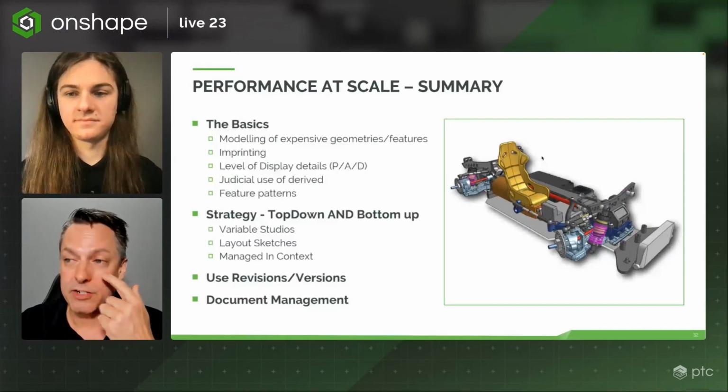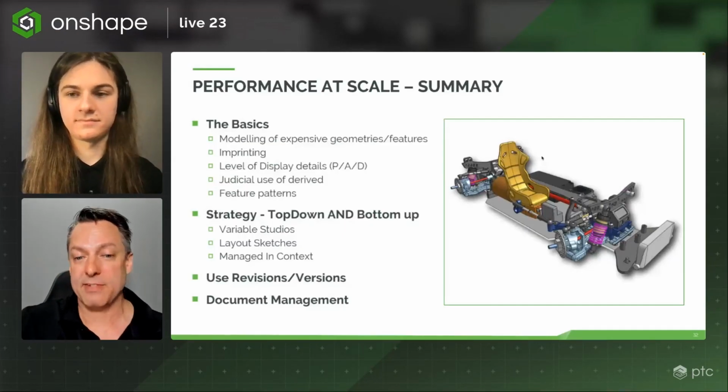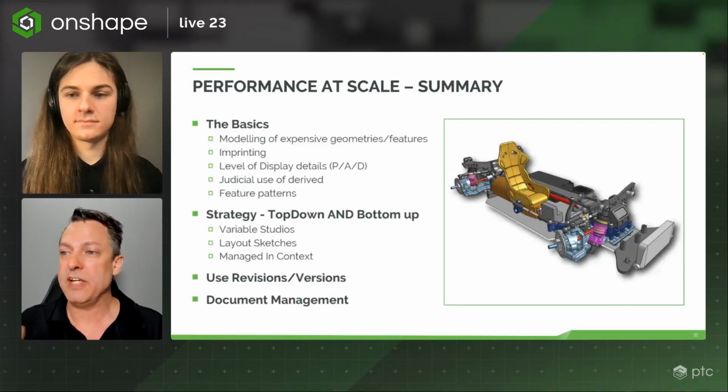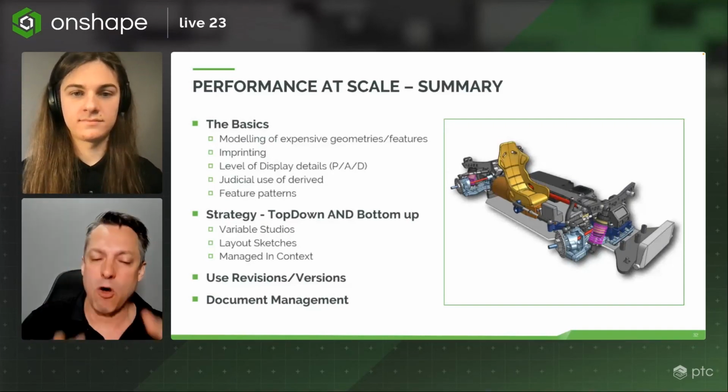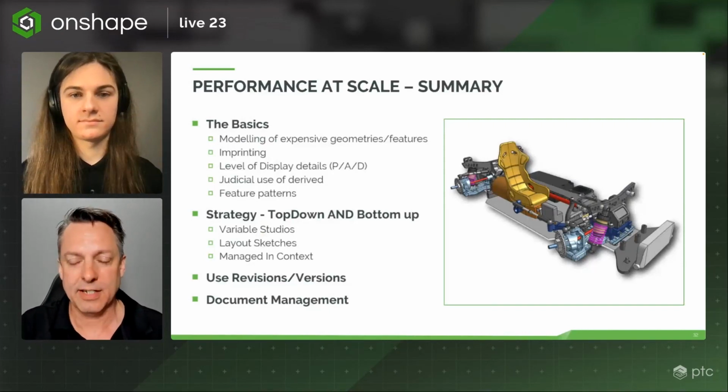So the strategies we're going to look at, we've already covered the basics here, right? So don't model expensive features, turn off imprinting on sketches if you're trying to create sketch on very complex geometry. That was the point that,